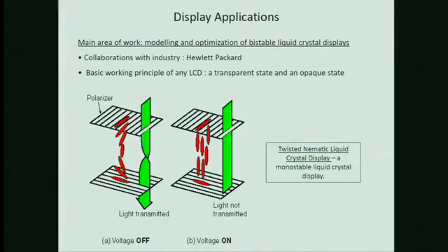Now, since this talk is really about the modeling of liquid crystal displays, I just want to spend a couple of slides very briefly describing the working principle of an LCD. And nematics have two key properties which make them very useful for display applications, like I've already said. They're optically anisotropic and they're very sensitive to external electric or magnetic fields.